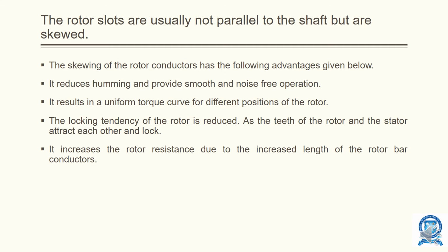It reduces the humming and provides smooth running and noise-free operation. It results in a uniform torque curve for different positions of rotor. The locking tendency of rotor is reduced, as the teeth of rotor and stator attract each other and lock. It increases the rotor resistance due to increased length of rotor bar and conductors.